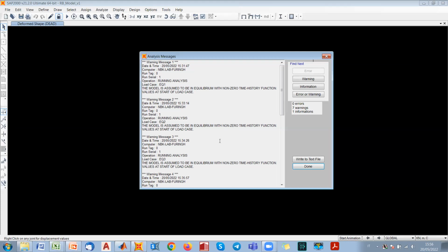Depending on the level of detail that we want to achieve. If you just want to perform some very fast computation, you can just consider an elastoplastic model with the hardening related to the rubber compound. But then there are a number of nonlinear links, for instance in OpenSees, which can directly model this hardening effect, also due to the high shear straining.